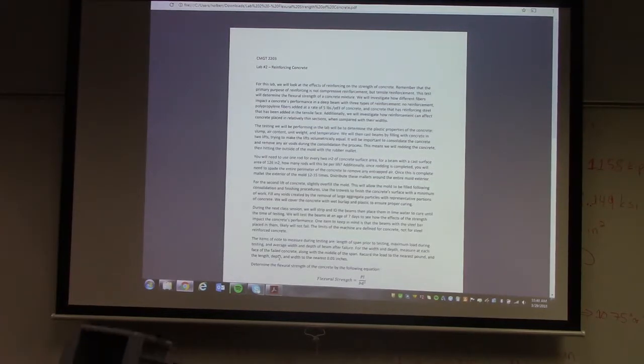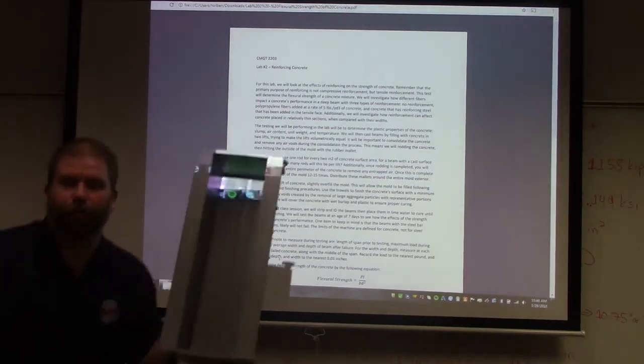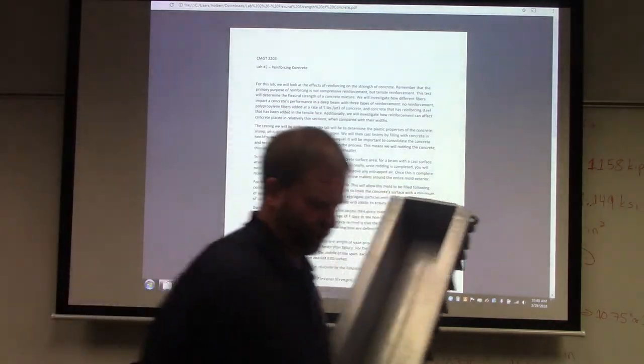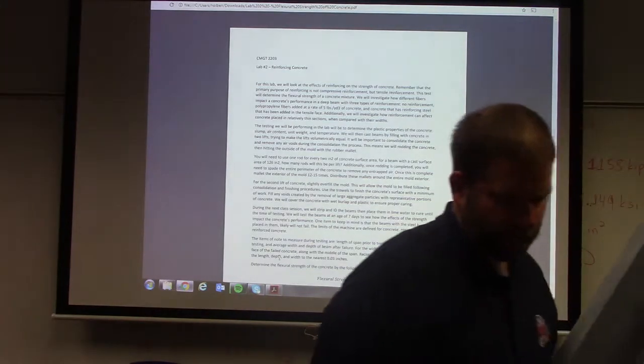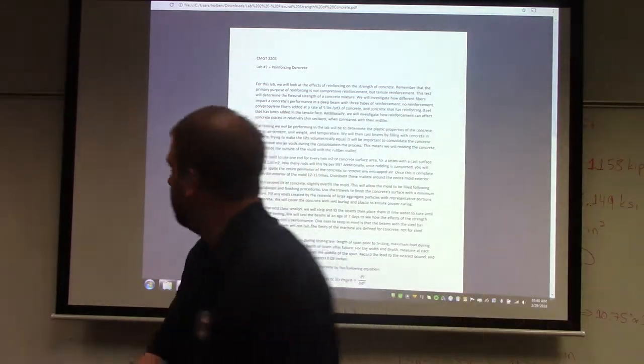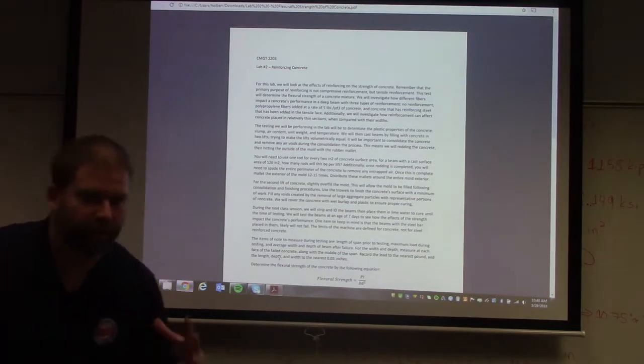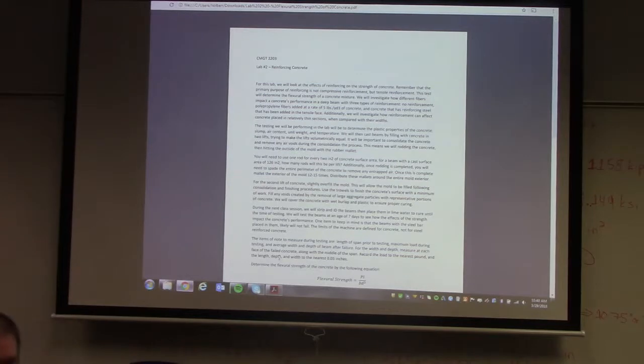So we're going to make 6-inch square beams. I think they end up being 20 inches in length. How do you suspend your reinforcing, your rebar? For the reinforcing steel, I'm going to make some templates out of plywood, so I can cut out holes in them and run the bars through. That's a very good question.